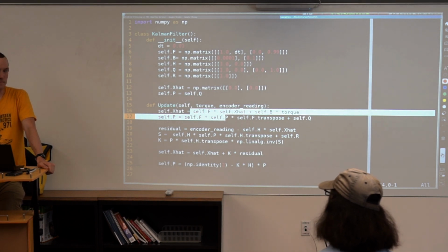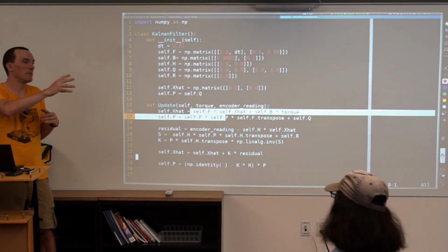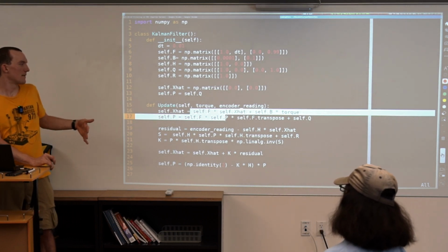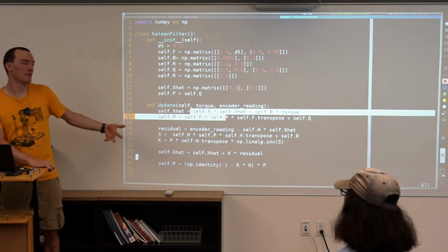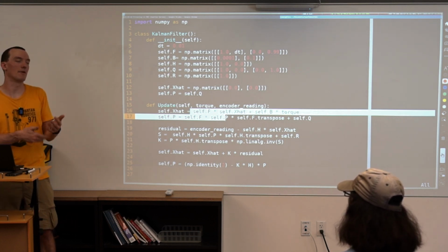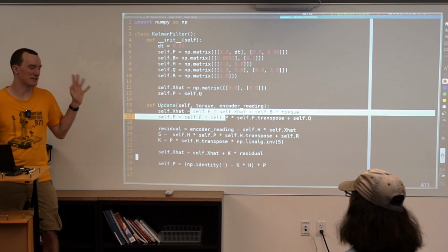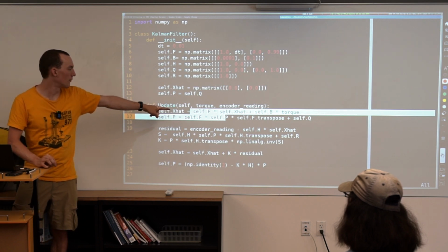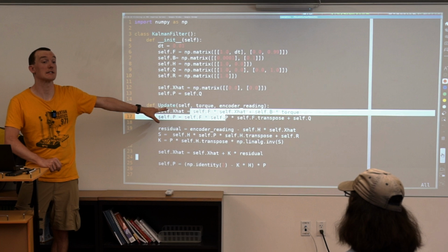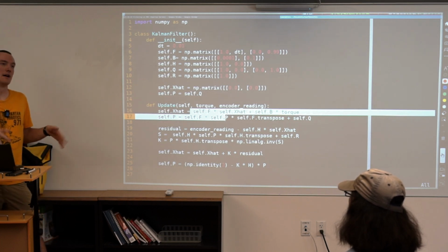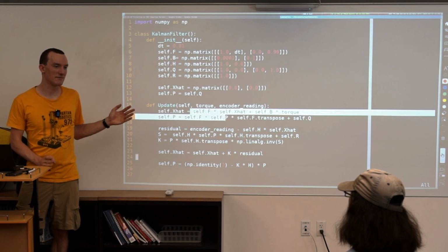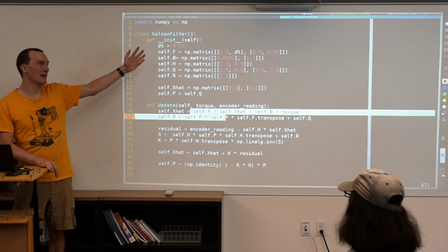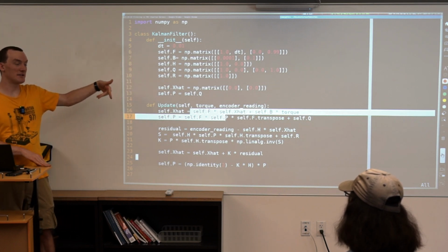And so you can run your actual robot, apply 1 volt or 5 amps or whatever to the motor, and look at what it did. You presumably need to have an encoder or something attached to it; most motors these days have encoders built in, so they'll tell you how it moved. You can compare that directly to what running just the model would have given you, and see where they diverge. If we apply 5 amps and it consistently moves slower and less far than we thought, you might have a mass number wrong. If it's something else, maybe you just have a gear ratio wrong.